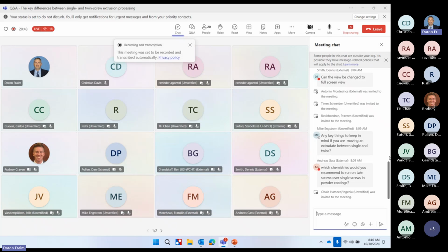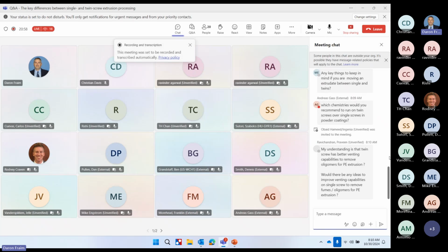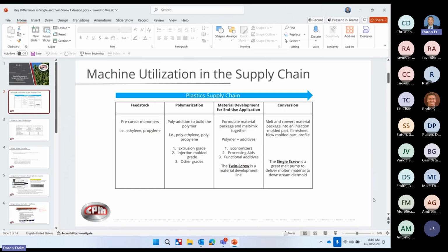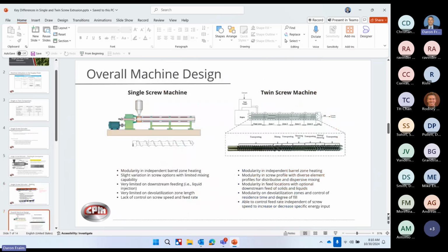I have worked personally with a single screw in compounding, and it has some capability of mixing, but it's very limited. Typically, very simple formulations are recommended. And so normally the mixing sections on a single screw are very limited. Let me just present right quick. I've got this so we can see this. I think a visual serves much better.